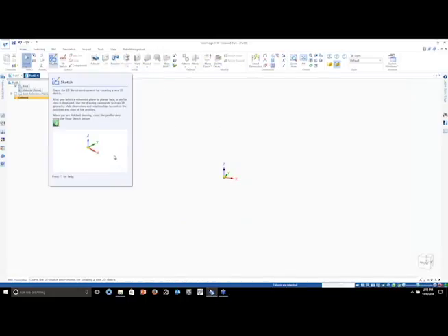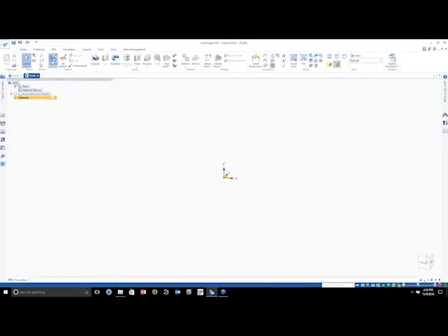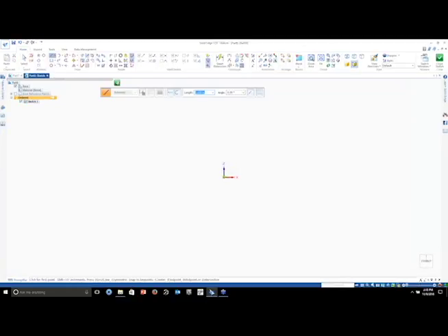All right, so let's start a new template here. I'm going to do the same thing in ordered. And again, you're going to have these templates, and you're going to have this video to go through in practice. So again, ANSI inch part and right-click, transitional ordered. All right, my menu bar changes slightly. So again, we're going to go into a sketch. So I'm going to pick a sketch.